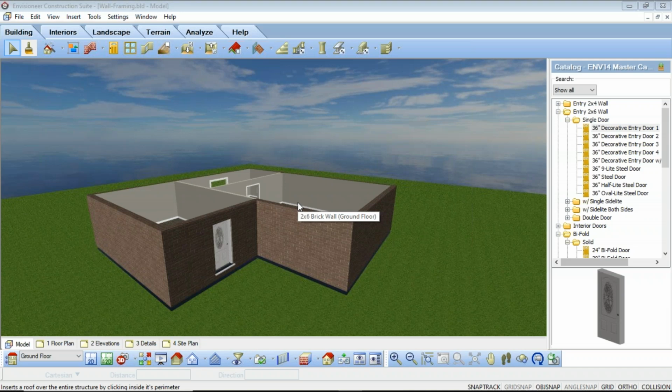Now, I do want to take a second to talk about intersection framing because we can't actually access it until we look at it in the model. I just want to talk about it here. So each builder frames intersections in a different manner, and that will change within a model from one intersection to the next, depending on its type and orientation, be it an inside corner, an outside corner, or a T-intersection. Each wall intersection in your model is framed using a standard intersection framing configuration designed specifically for that type of intersection. Intersection framing configurations are stored in an internal library called an intersection lookup table.